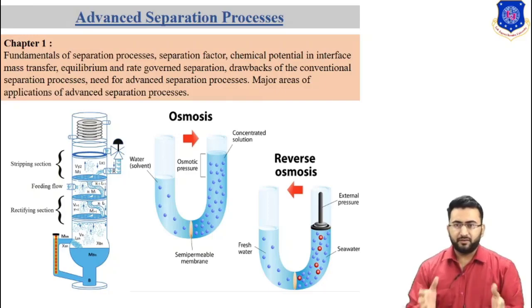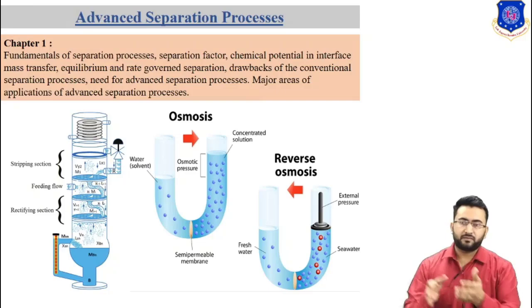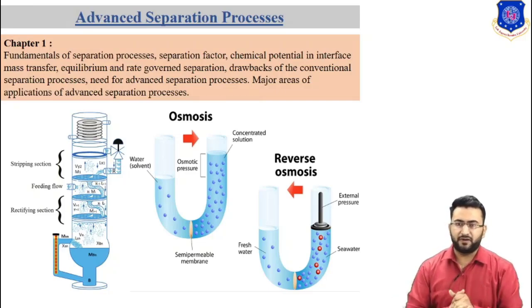In distillation, by applying heat, we can separate both components, and both components are in equilibrium in the vapor phase and liquid phase. In liquid-liquid extraction, both liquid components are in equilibrium when adding the third component C, which makes the separation possible. So this is one type of equilibrium governing process.